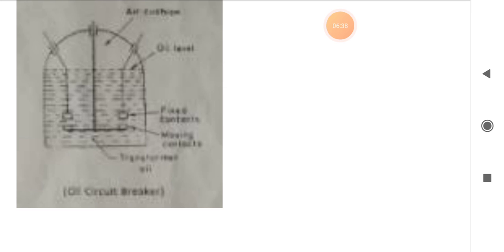Because if we deal with higher voltages and suddenly disconnect the supply, then flashover will take place, resulting in sometimes death of the personnel who has switched off the supply, or the machineries might also be burnt out. So for handling this high capacity of voltage, we have to switch off in a medium, and this medium here is oil.